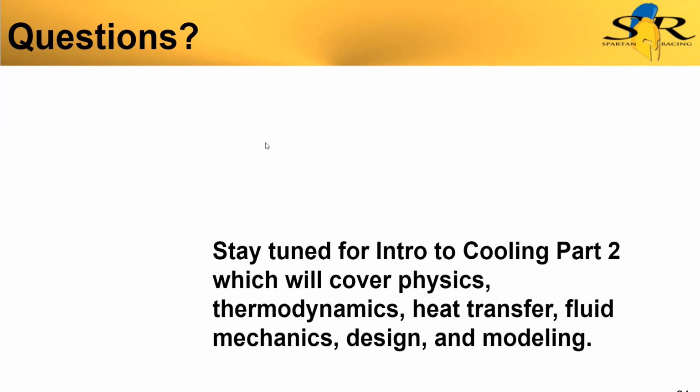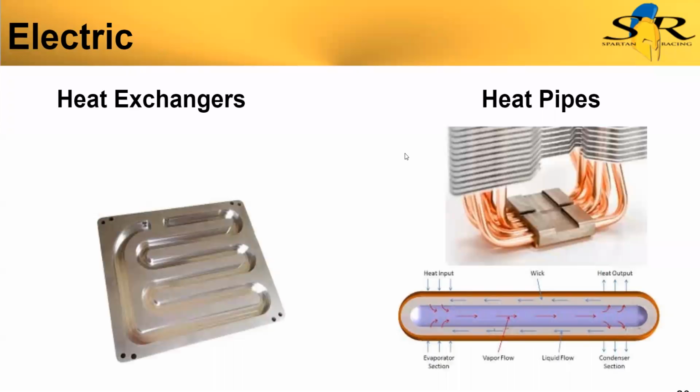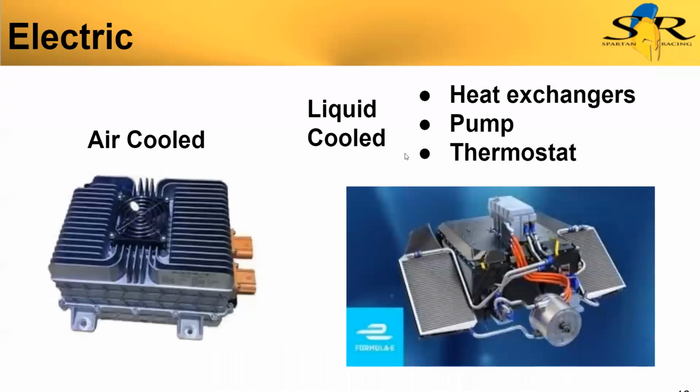Yeah, I have a question actually. Can we go back to the heatsink part with the fan for the electronics? Yeah, there you go. Here, the air-cooled one. On this left image, is the reason they usually put the fans in that direction just because of packaging? I guess that will distribute air through the fins, right? You don't want it to go towards the fins, you want it to go through the fins. Right, exactly. So it's usually packaging, but ideally you would put it through the side, right? Right, yes. In this case it was probably packaging, but the idea is to get the air to flow through the fins. Gotcha.